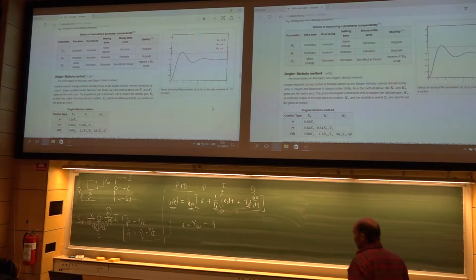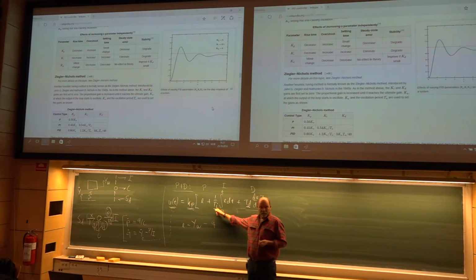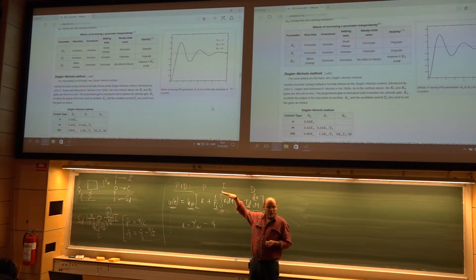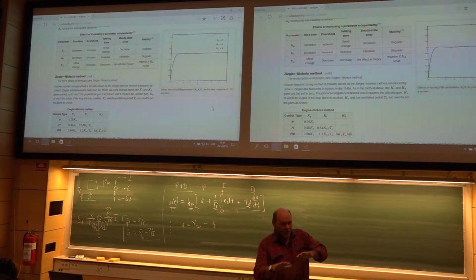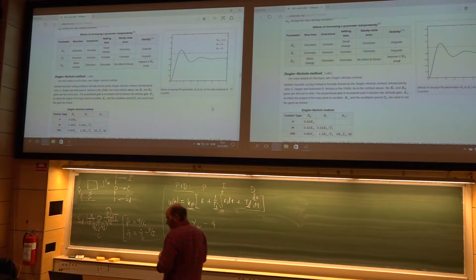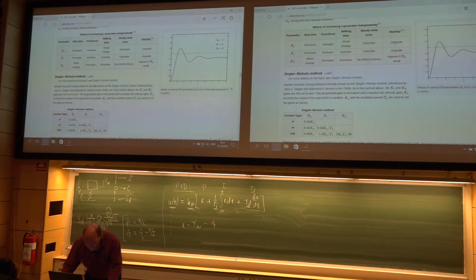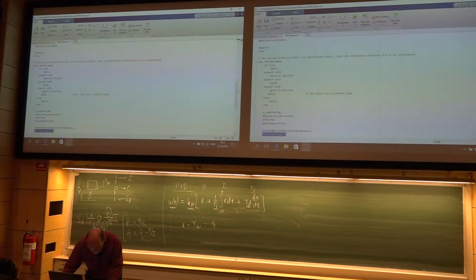The integral term will then be used to adjust the offset if you are not hitting the correct level. Finally, the damping, the differential, he will smooth things down a little bit so you avoid all these stupid oscillations. That's the theory. So now we can start playing around with this in my code.